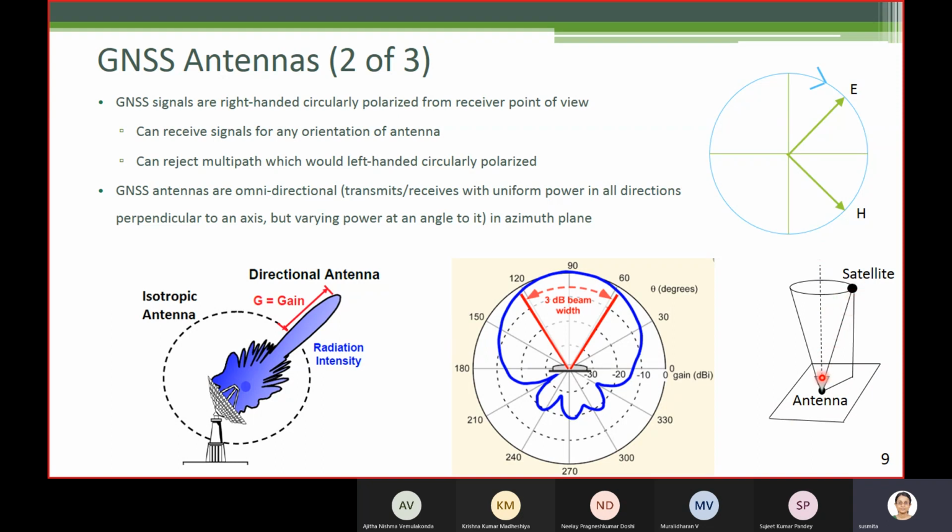You just imagine a vertical plane considering this line and this, and then extend it on the other direction, here also. So for the right half of the plane, you have one azimuth. For the left half, you have another azimuth. Basically 180 degrees minus the azimuth of the right half.